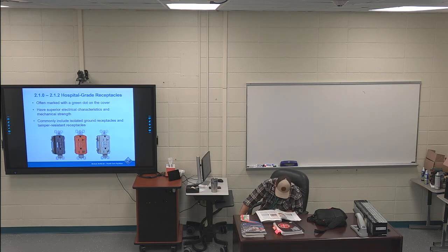The first sentence, a long sentence, is highlighted. NEC requires that each patient bed location in a critical care space be provided with a minimum of 14 receptacles, at least one of which must be connected to the normal system branch circuit required by the NEC, or a critical branch circuit supplied by a different transfer switch than the receptacles at the same location.